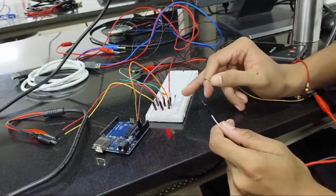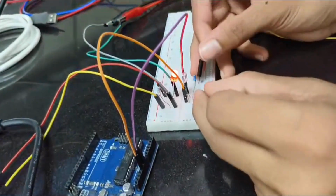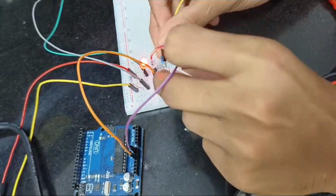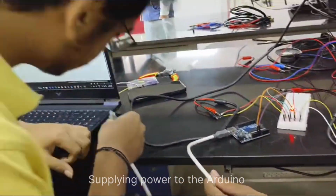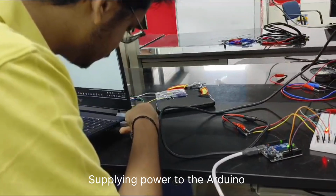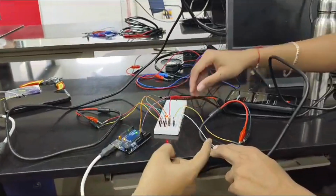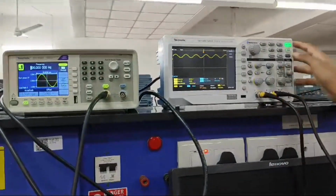We have connected the photodiode in series with the 10k ohm resistor, and we are connecting the oscilloscope wires to read the output. We are giving 5 volt input from the Arduino, and here the bulb below, and we will read the output through the oscilloscope.